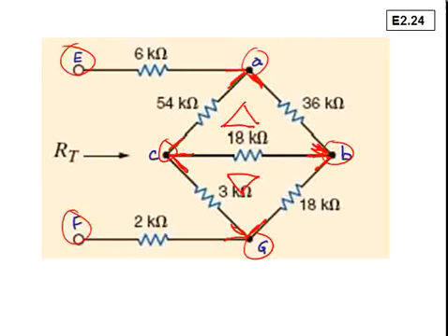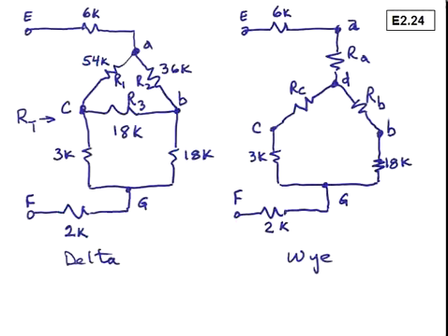So in order to do a circuit reduction, we'll apply one of the transformation processes. Let's choose the upper delta mesh to perform a delta to Y transformation. Here we've redrawn the delta equivalent circuit. We've labeled the R1, R2, and R3 values in that circuit. We've made the bottom delta configuration more rectangular so that we can see what we're going to develop as we proceed to the transformation to the Y circuit.